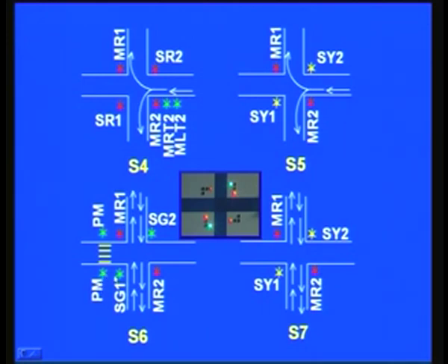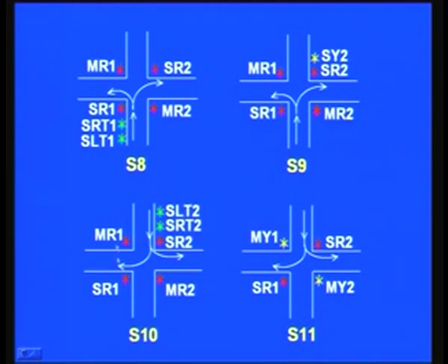Next, here you can see that the main pedestrian crossing is lit, the signal is lit here, allowing the pedestrian to cross because this is going to be straight traffic. In addition to this left, we can also provide the same thing here; we can duplicate it if you want this crossing. You do not need any extra signal for that. Next is once again a yellow traffic transition, and after this we have the S-side sequence, which will be the same case for left and right traffic from the side roads.